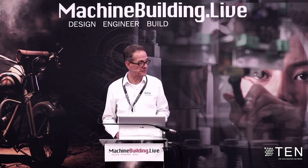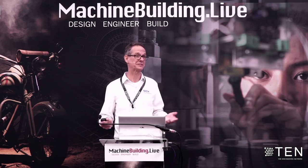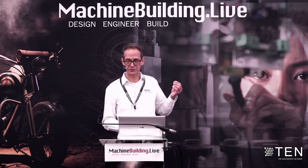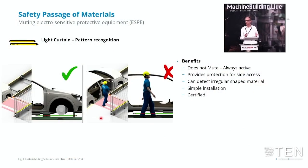Now, the benefit of this system is that actually it's a contradiction to the whole presentation because it doesn't actually mute at all. It's always active. It merely recognizes patterns moving through the entire length of the light curtain and looks only for pattern disruption. So the system remains active in terms of protection at all times.